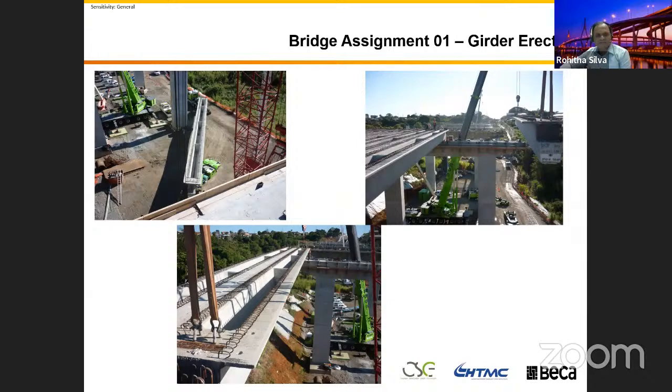There was a comment in there saying we do not use drainage below expansion joint in Sri Lanka. I think if you are using a strip seal joint, you may not use the drainage, but if you are using a finger plate, you must use the drainage. But still you can go and retrofit that one, but it's very difficult. Yeah, there's a way to do that one.